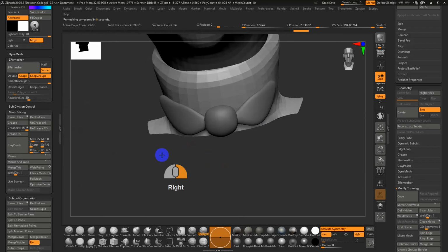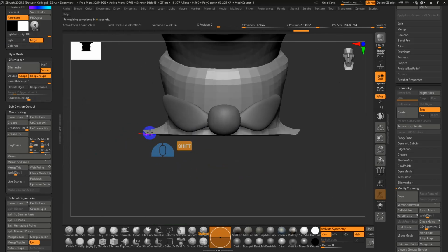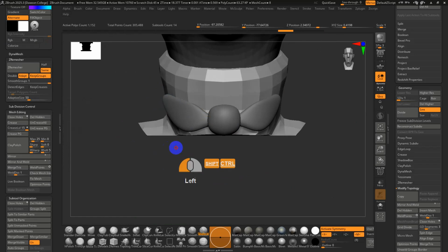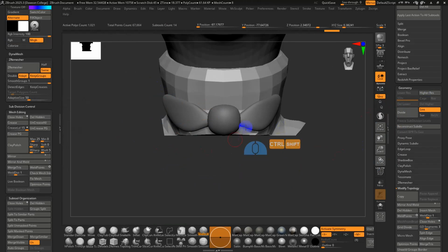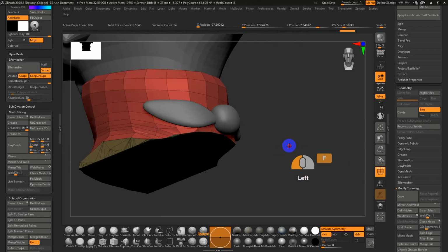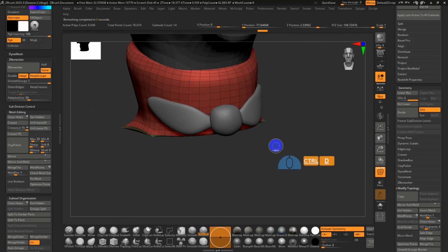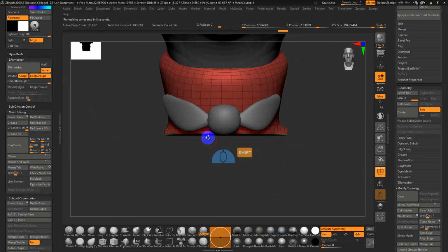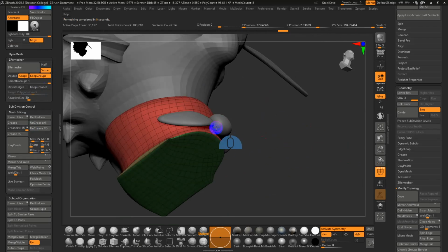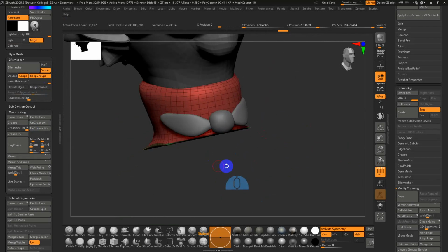Okay, so that should give me much cleaner polygroups for divisions, so I shouldn't have any weird errors, right? The other thing is I typically will want to avoid very thin pieces like this too, so I'll undo the remesh and just maybe slice one more time just to clean this up. There. Okay, so again, I'll remesh, keep it about the same. That's pretty good, and then I'll hit Control D. Now, if I still feel like there's a bit of an issue, I might try to slice, but I'll save that for later on when I'm going to trim this up to make it perfectly flat.